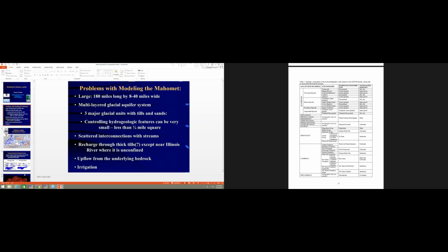That can actually go a bit awry from time to time, like the Maquoketa, we call that a shale. But there are some communities that use a limestone unit that's very thin within the Maquoketa, the Fort Atkinson. It's just so local that we don't really worry about it in the model. But for those communities, our model's not going to be able to do anything for them. There are some things we can tweak, but yeah, we try to lump as much as we can.